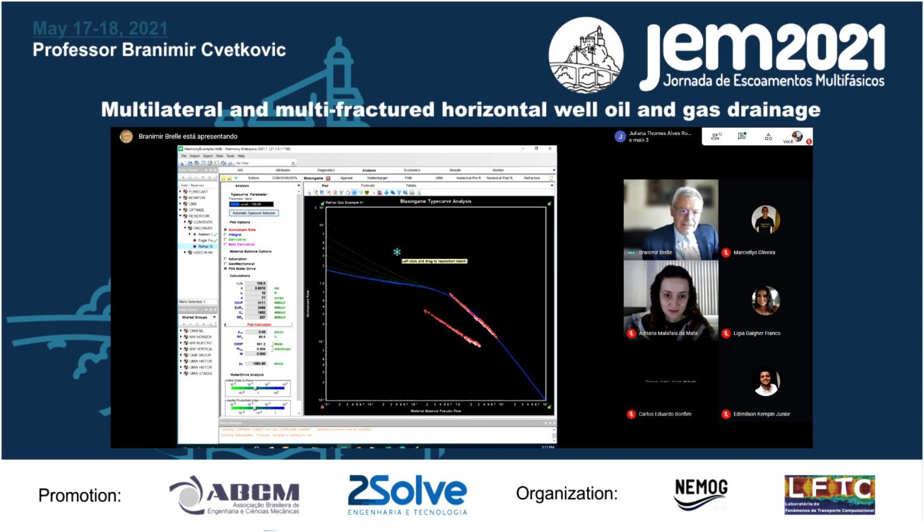But anyhow, when you have a reservoir with this initial water in place, you will know how much water is coming per certain time unit into your place. And you will also know the aquifer, what is the volume of that, and what is your productivity index, how much water you will bring with the time in your system, which is the oil reservoir. That is how much and how fast you will include pressure into your system.